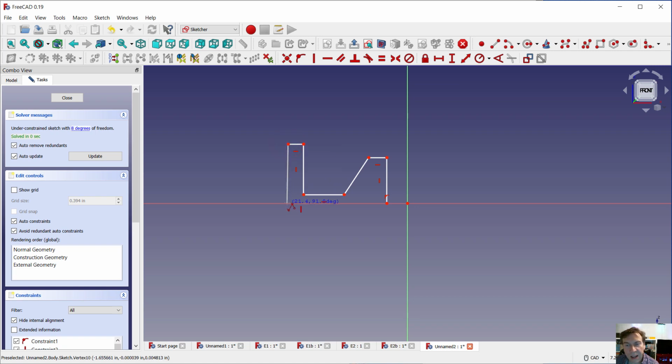Drag down. And now you're looking for two entities. You're looking for the line below there to turn yellow, as well as a vertical line. So it's adding coincident and vertical to the geometry. Click. And now you could go ahead and you could right click and it will end the line chain. You could also hit escape.